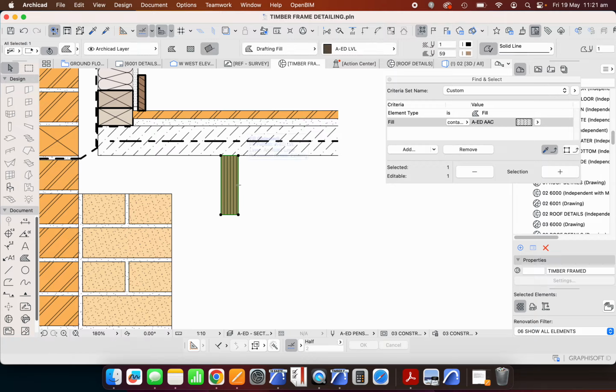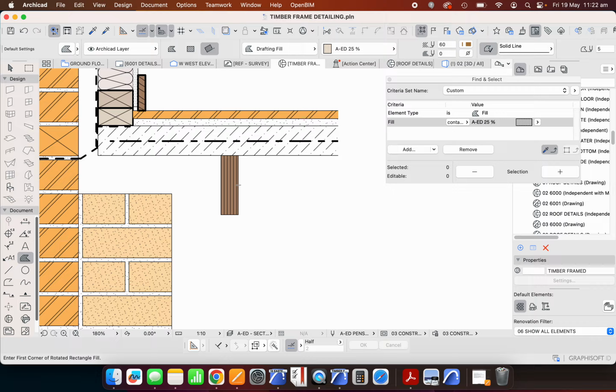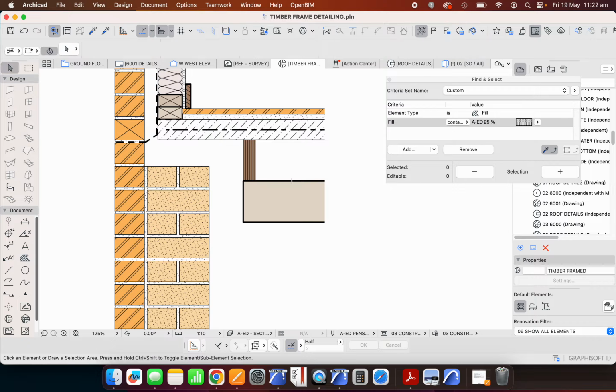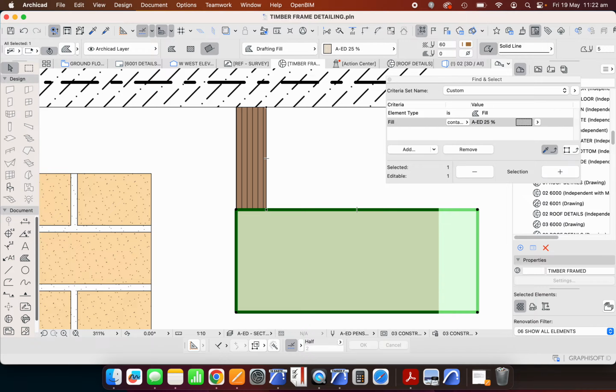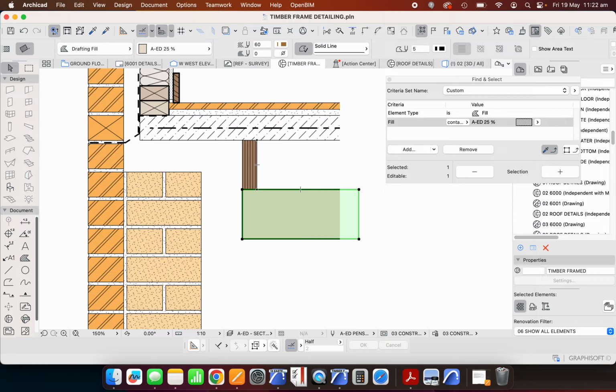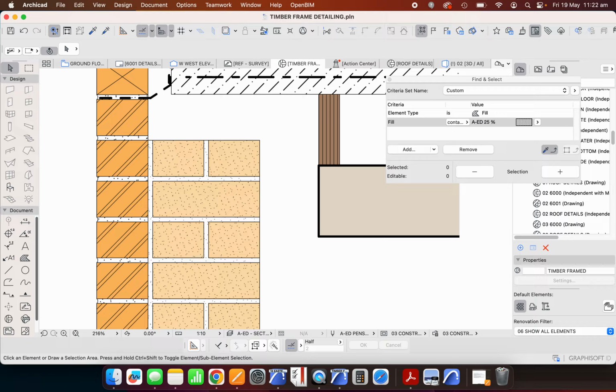So we've got an LVL, in this case in section, that's the floor joist, and then we've got an LVL in elevation, so that's going to look like this, which is spanning the other direction. It's also going to be 150, but thicker. It's going to be a 75 millimeter thick bearer, whereas this was a 45 millimeter joist. Now, because the bearer is in elevation, not in section, it's also a thinner line. Same with the brick idea here.